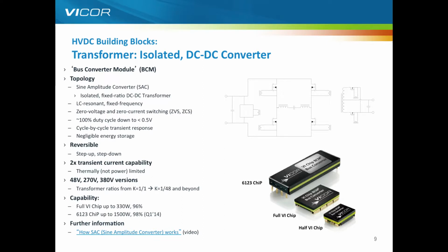In this topology, we have full zero voltage and zero current switching, which means that we can continue to optimize the efficiency of the whole device due to the fact that we don't have to deal with any trapped gate charge or other parasitic elements within the MOSFETs.